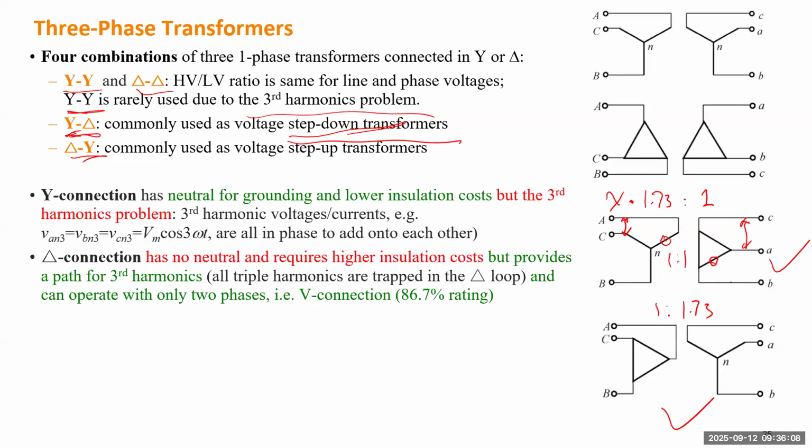The better idea is that the transformer will split the entire network into sections, depending on voltage level. So in each section, it's better to have at least one Y connection. Okay, so it can be delta to Y and Y to delta. Even if you have delta to delta, the next one is better to use Y. So any section you need to have at least one Y. That will give the simplest design while still keeping the neutral wire for each section.